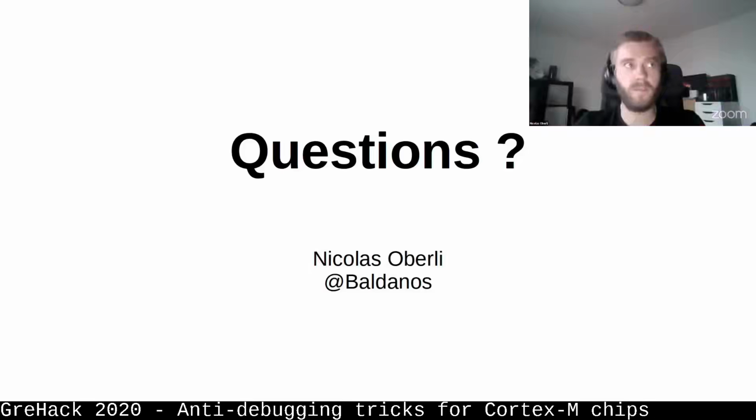Well, when you set up a breakpoint instruction or you use a hardware breakpoint, it will call the debug event handler first. And if you don't have a debugger attached, that event cannot be used. So the core will raise the exception to the hard fault, which is the ultimate fault that you can have. So this is the way we do it, by forcing the core to execute the debug event. And since there's no debugger, it will raise to the hard fault. And this is how you can detect whether there is a debugger or not.